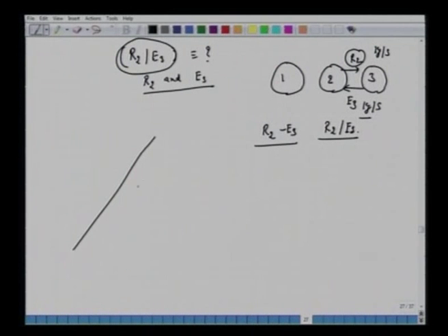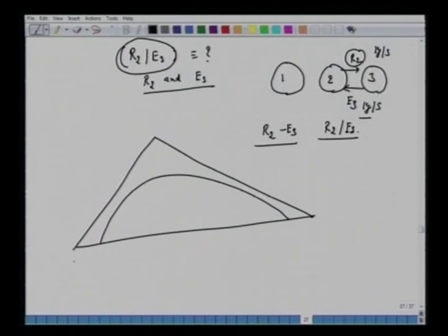Again, visit this equilibrium diagram which you have plotted previously. You have the phase diagram like this. This is A, this is B, this is C. You had feed. It had intersected, say, E1 at 0.32. We had extended this here. The solvent, this raffinate was at 0.05.